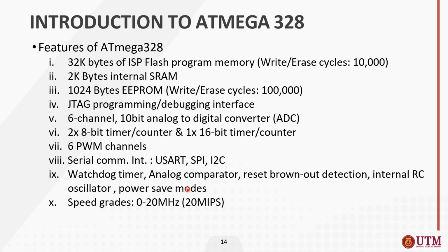The watchdog timer is a specialized timer used in microcontrollers and embedded systems to detect and recover from malfunctions or software faults. Its main purpose is to ensure the system operates reliably by monitoring the execution of the main program. If the program hangs, crashes, or enters an infinite loop, the watchdog timer can reset the microcontroller. It means the error from an infinite loop and so on can be recovered, and the operation restored.